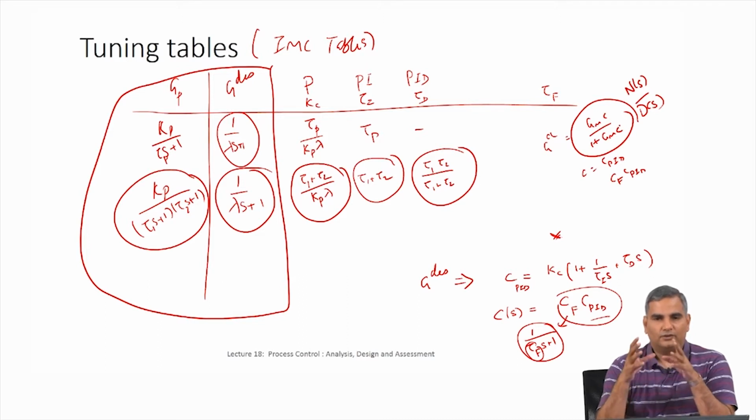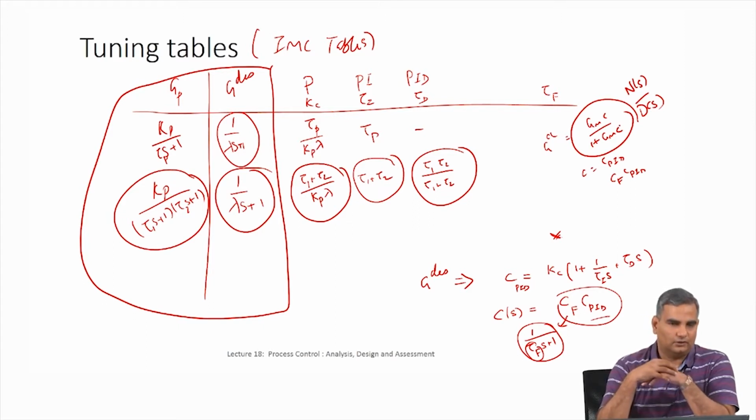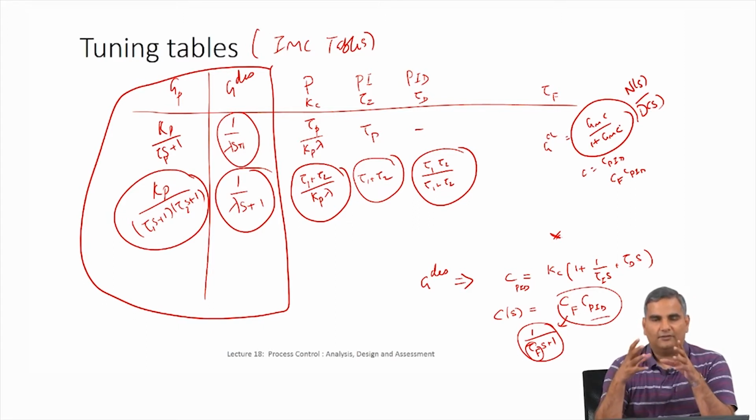And I also said when you think about state space models, you could have multiple states but you can still look at single input single output control systems. Anyway, after that we solved these state space models in the time domain, and then showed that the output will be in what is called a convolution form or a convolution integral.